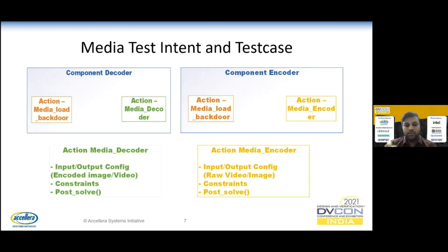So then it dumps out all the output reference data. We have golden reference data, and then we have to compare bit by bit, wherein the output generated data matches the desired golden data or not. All of this is also taken care of with the scripts, which just run it in the test content, generate it, and give us the data.